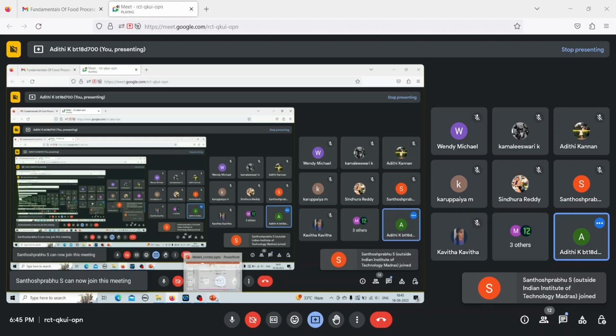So you need to first understand, unless and until it is mentioned, do not assume that it is an agitated film evaporator. I know there was a question that mentioned a falling film evaporator used for highly viscous food product, but there it was specifically mentioned that it was an agitated evaporator. But generally, falling film evaporators are also possible without an agitator.